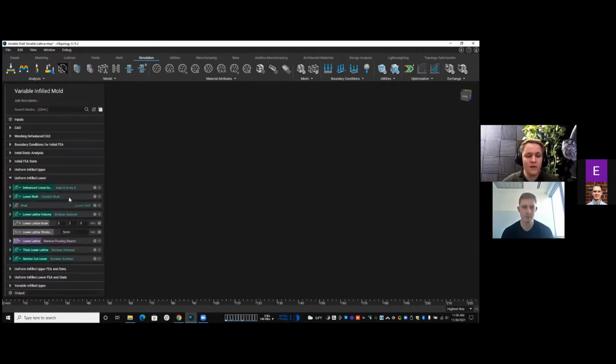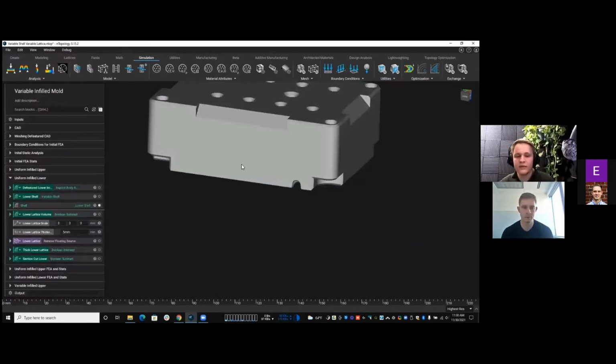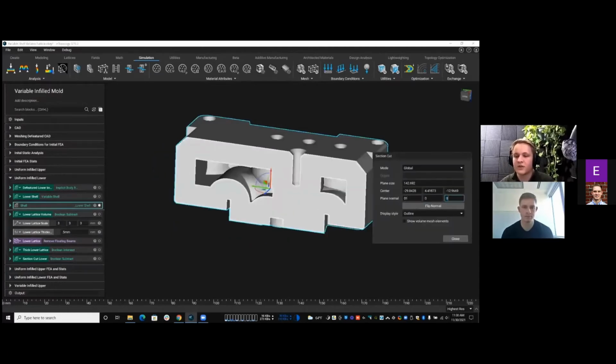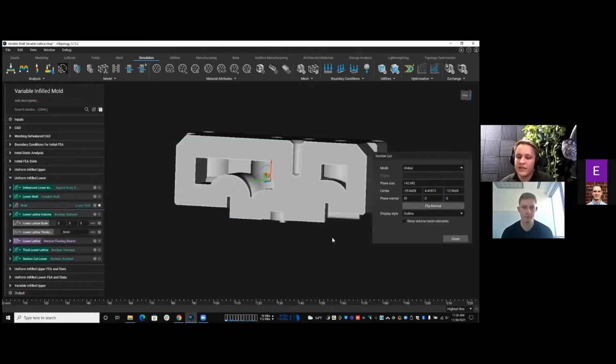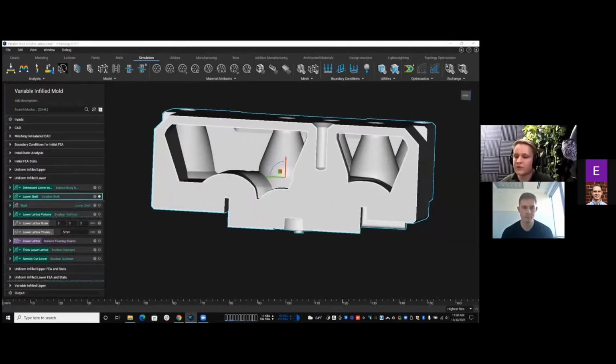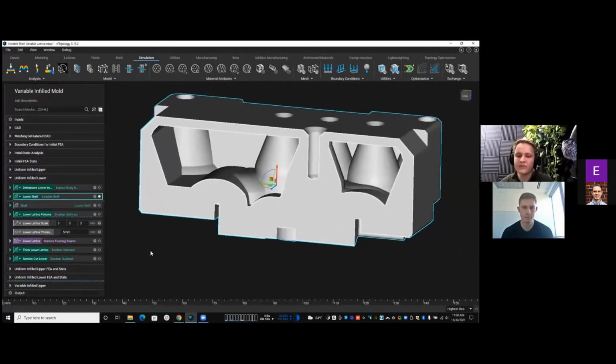The first thing I did with the lower, I took that part, I created this shell, right? This is the upper here. I create the shell, but in this case, again, I start with the uniform shell. And in this case, we have some pillars that are running through. So they have that nice wall thickness happening as well. And the uniform shell, again, not quite good enough. We're going to switch. We're going to go over to this variable shell here. Right? Now we have some room to work with.